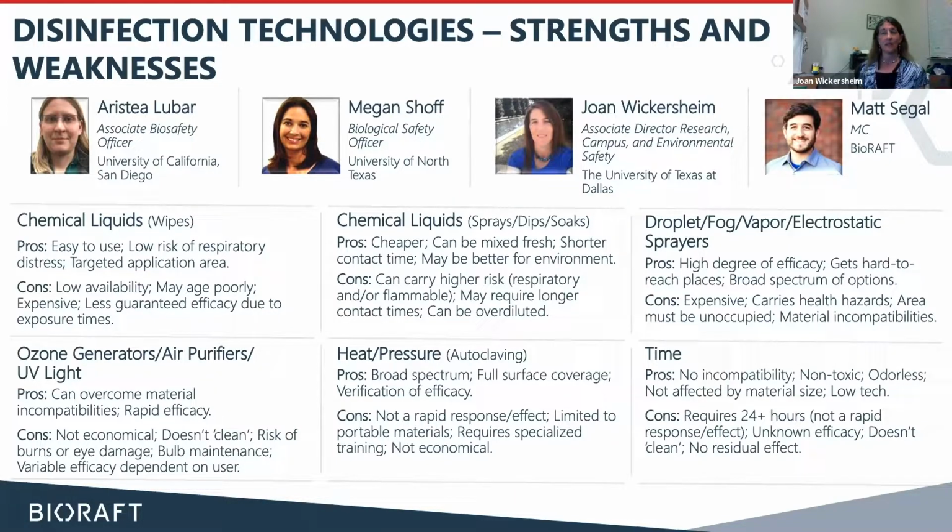I have seen a lot of the different information that's out, starting with the Princess Cruise, the Diamond Princess, whichever one it was. We found viral RNA viable up to 17 days later. And that was where we started with this thing: oh great, now do we have to keep areas empty for 17 days? But to go back to the 24 hours specifically, that cut point is typically what we're using, as we feel that after 24 hours, the ventilation has been adequate to remove the aerosolized viral particles that may actually cause infection from the air.